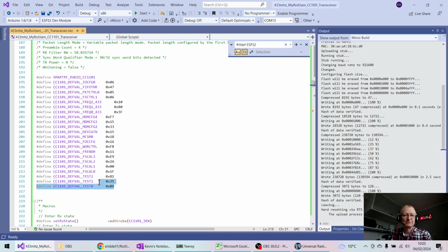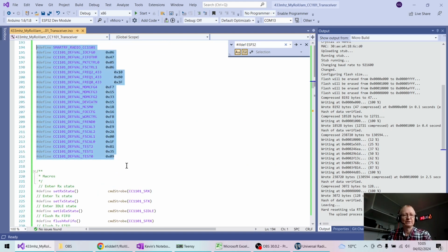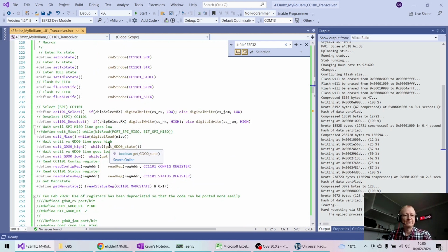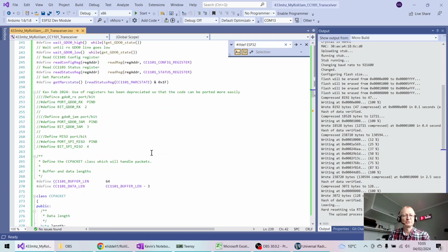So, but these clearly work for the QiaChip. This is all the same. I did alter some things so I could port it over. It used to use this sort of code because it was bit bashing the registers in the Teensy, and I wanted to make it an ESP32 version. So I've just changed this here, and another version down below.